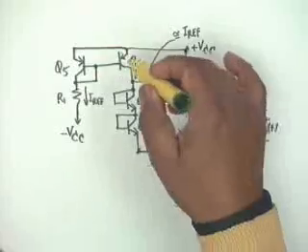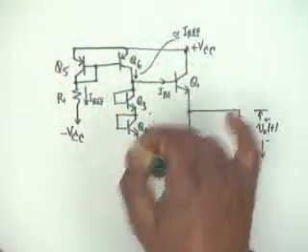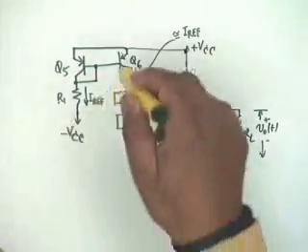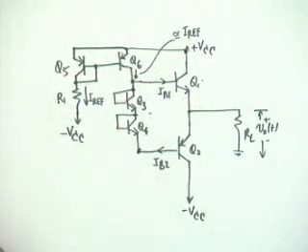Because the larger the current drawn from the transistor, the more will be the dissipation and the more will be the junction area required to supply this current. Otherwise the transistor will burn off. Okay? So the emitter junction area for Q6, Q5, Q3, Q4 can be much less as compared to that of Q1 and Q2. Now what does this affect?